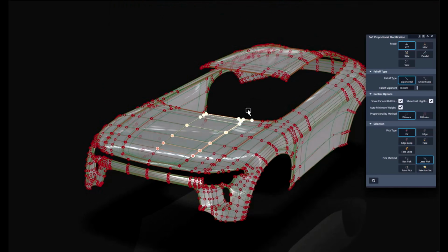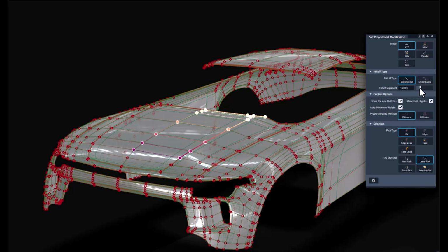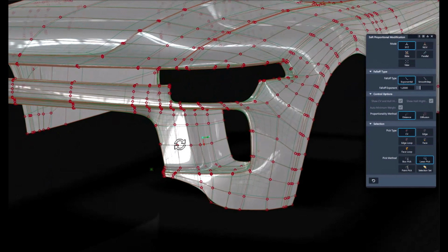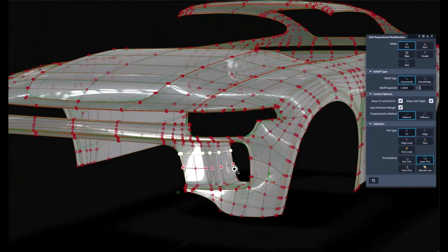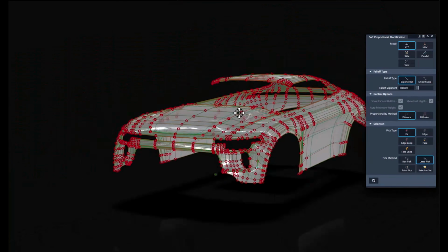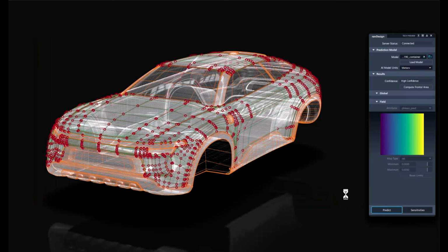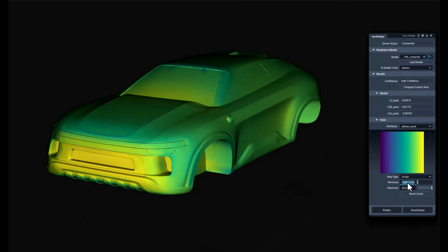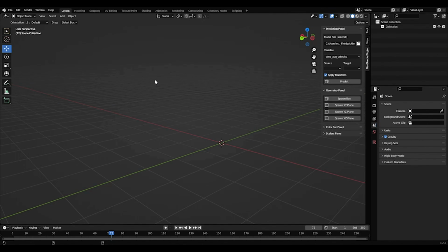I mean, you can also apply something like a lattice box morphing, sorry for that. You are basically free. You can apply larger changes. You can also apply smaller changes if you want. And at the end, if you're satisfied with your work and you want to see what's the delta, what's the next drag coefficient, you just mark everything you want to take into account, run the next prediction, and move on with this information. I think that's the idea. This works on subdivs, on NURBS, also works on meshes.